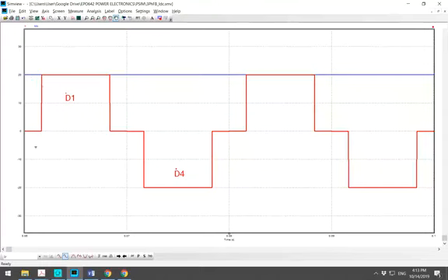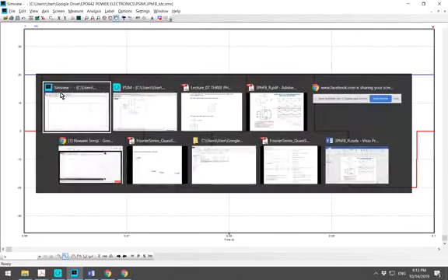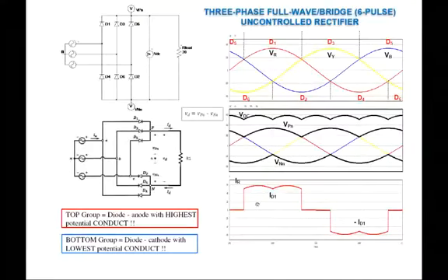And so therefore, if you look at the angle, if you refer to the first slides here, that will be when the voltage VPN is 30 degrees, and then we have 120 degrees, the pulse of the phase supply voltage. So that will be 150 degrees, and then you have another 30 degrees, so you have 60 degrees here, so that will be 210 degrees, and then you have a further 120 degrees, so that point will be 330 degrees, and finally you have 360 degrees.